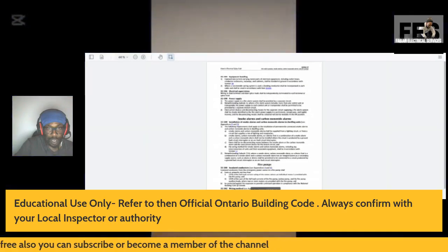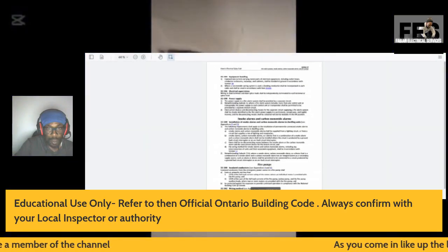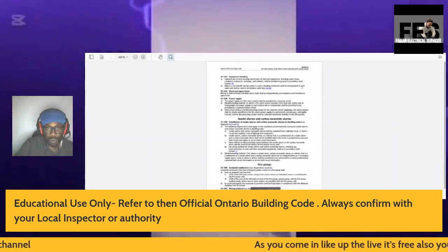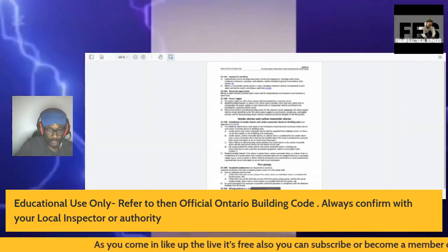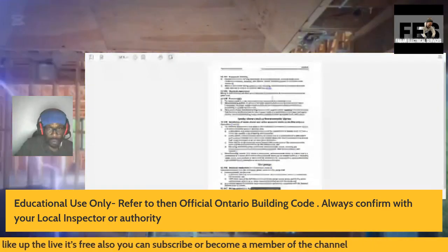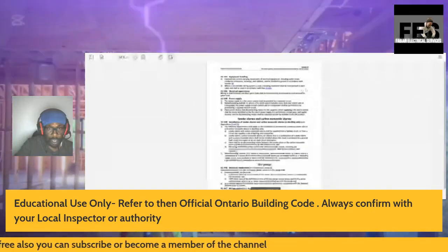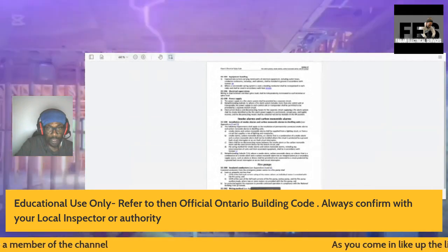So that means the boxes, metal stuff, Section 10. Where a non-metallic wiring system is used, a bonding conductor shall be incorporated in each cable and shall be sized in accordance with Rule 10-16.